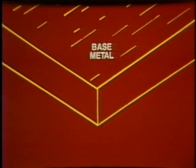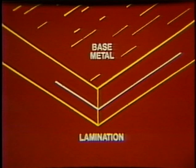Other conditions of the base metal which may impair the ability of a material to perform as expected can include laminations, delaminations, seams, laps, and lamellar tears. Laminations are generally a flat, elongated sandwich discontinuity normally found near the center of structural metals and are caused during production at the mill.